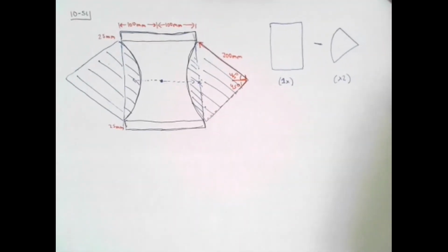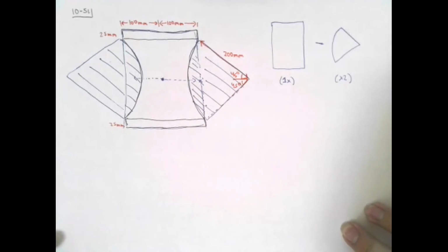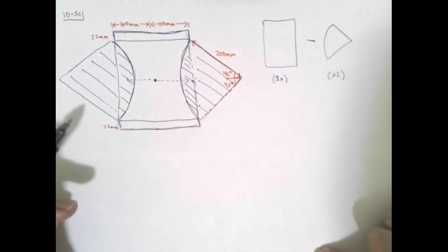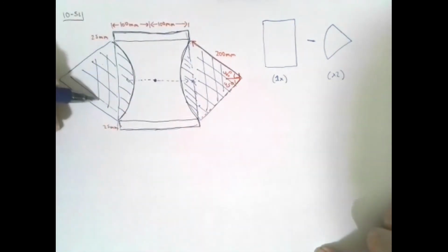So what can we do? What do you think? If we remove the moment of inertia from this element, what do you think we could do to make up for it? Could you just add the two moment of inertias of the two triangles? Exactly, right? We can add the moment of inertia about the centroidal x-axis of a triangle.